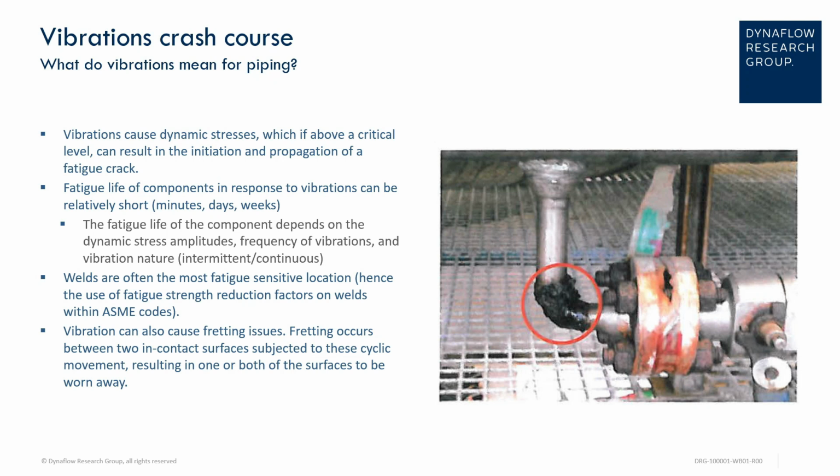Welds are often the most sensitive locations when it comes to fatigue, and vibrations can also cause fretting issues, where fretting is the wearing away of surfaces in contact due to cyclic movement.